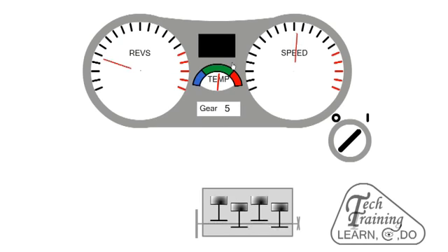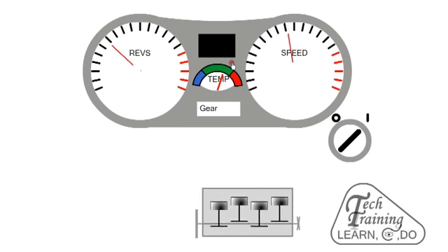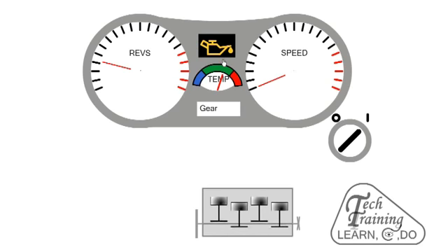If the oil is not changed at the recommended interval, its viscosity can change. Oil pressure is lowest when a hot engine is allowed to idle. An abnormally low oil pressure usually indicates a worn engine, as leakage from the bearing clearance is faster than the pump delivery rate. However, it could also be a low oil level, a failed pump, faulty pressure switch, or a blocked filter.